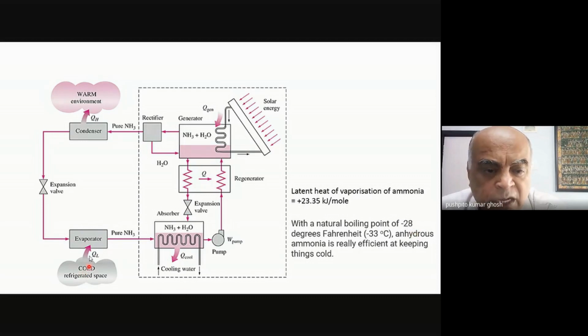And that's how these systems then become refrigerants, and they can extract the heat from, let's say, the space which I want to cool. So that's really the evaporation of a liquid which is becoming vapor, drawing the latent heat from the rest of the liquid, and the rest of the liquid is cooling down.